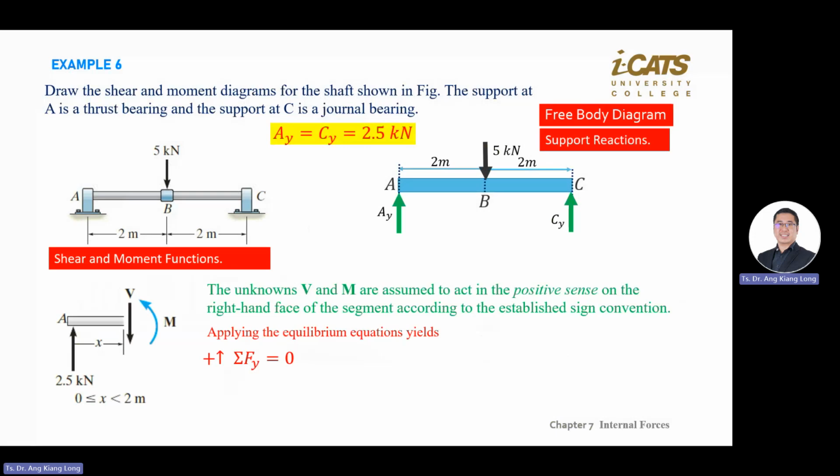So you will get an equation. What is V? If you use the y equilibrium equation, all the Fy equals 0, so you'll get one equation. Because we have forces and moments, you use the force and moment equilibrium equations. So here Fy equals 0, and moment anti-clockwise is positive at A, because we start our x here from A and then continue until point C.